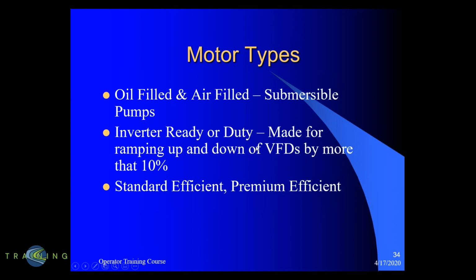Inverter-ready or inverter-duty motors are made to say that it is able to be run on a VFD. Most new motors are VFD-ready or inverter-ready. Older motors mostly are not. So if you have a customer that's putting a VFD on an old pump, they need to make sure that motor is sized and inverter ready so that it doesn't overheat the motor. The insulation is different and it will be required to be different for those VFDs.